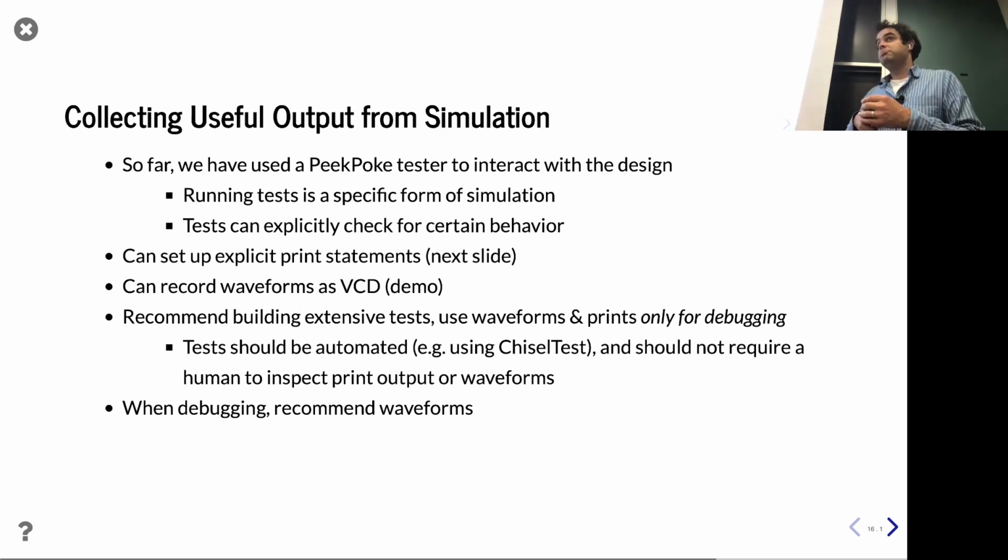Looking at print output, oh yeah, it did the right thing, it printed the right thing. But you, the human, are checking that, right? And so, although that's helpful for day one of developing, after that it's actually not as useful as you think, because every time you want to see the thing is correct, you look at the output and have to remember what the right value at the right time is. Is that the right output? I don't know. Encode that memory, that information, into a test bench. So if the test passes, as far as you know, it passes this test, right? I don't need to remember, when I run my module or my program, what order things should print in, and in what way. That's what a test is for.